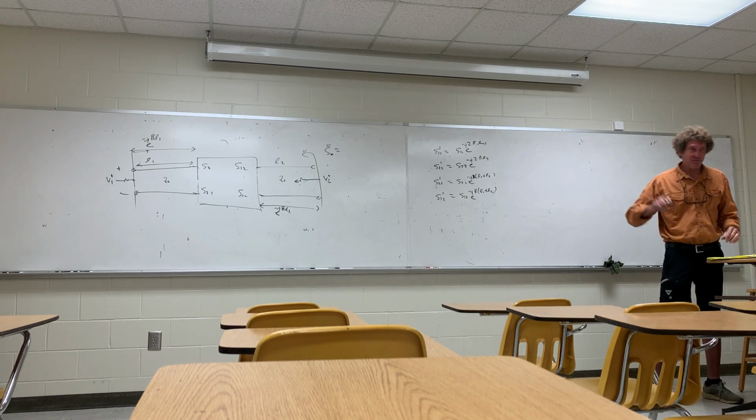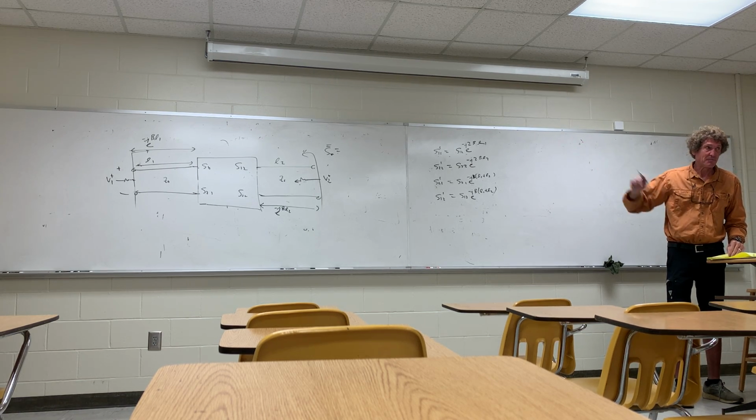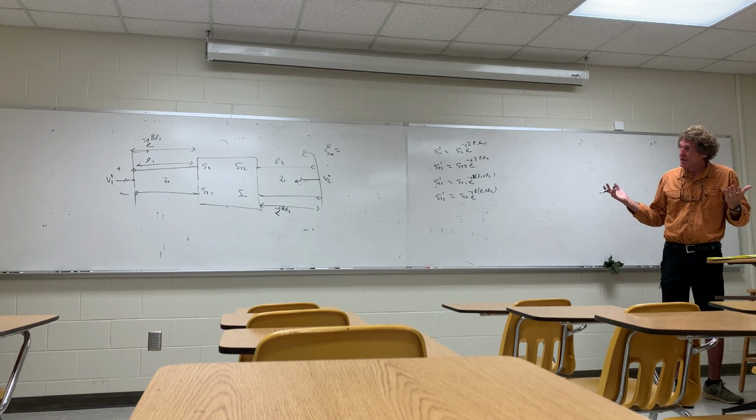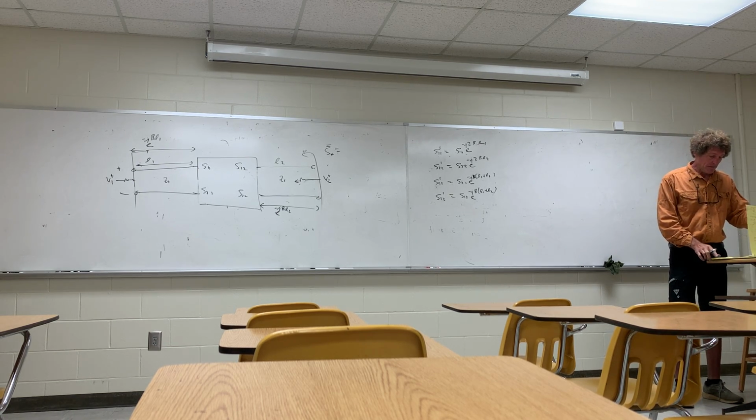We had to use a shifted reference plane. And that shift in phase is a function of frequency. Remember that: beta changes with frequency. So the electrical length and phase will change. It may go from maybe 30 degrees up to 80 degrees of phase change over a select frequency band. All right. That's phase shift.